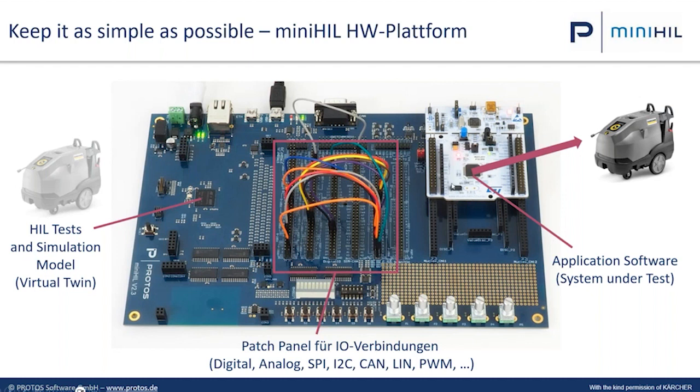And the system under test is usually the microcontroller here. And we connect all the pins of this microcontroller where your software lives. We connect it over this patch panel with the test system. And in this case, you see one of our customer applications here. Usually your microcontroller controls your system, but in order to test this, we simulate the environment with all the interfaces, the motors, the batteries, and so on, and make basically a virtual twin of your hardware and of your environment, and simulate the complete environment.